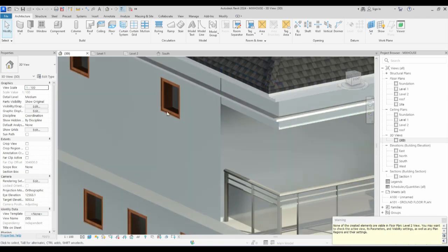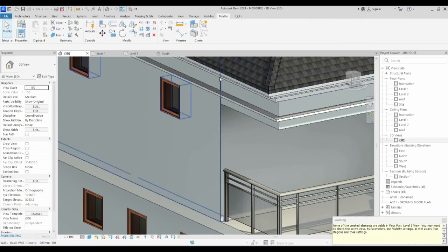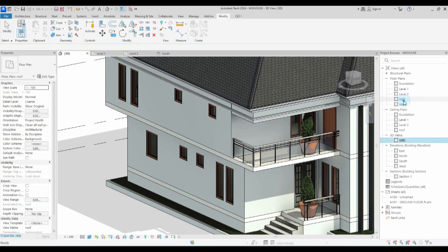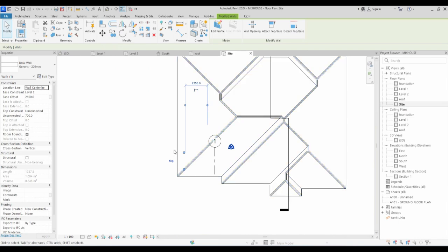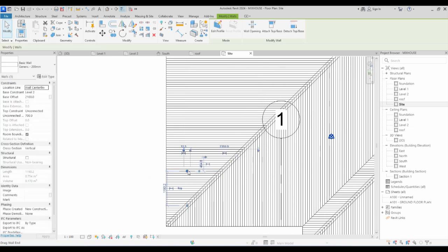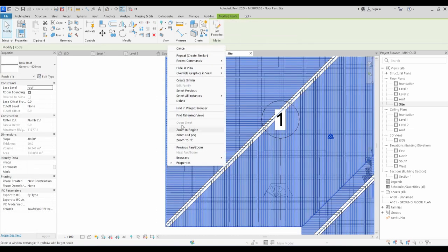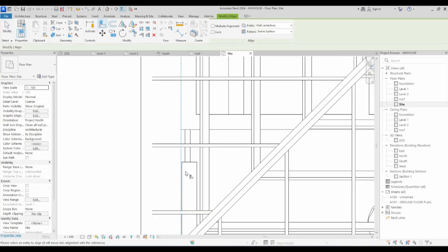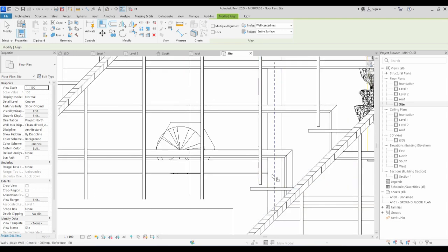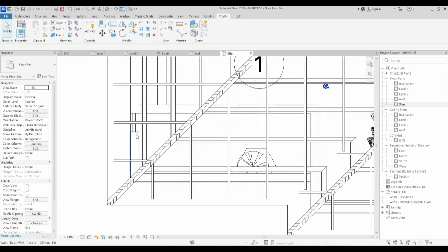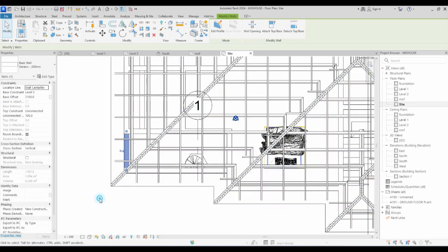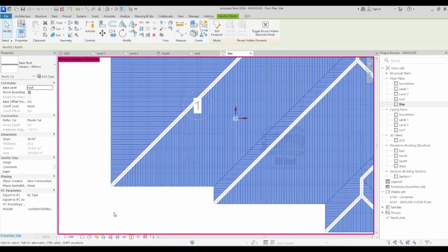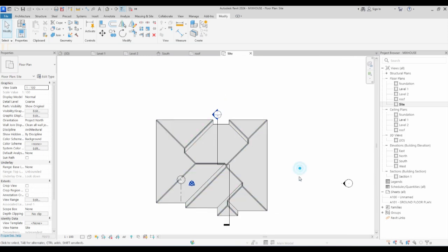So what else do we need to do? You can now align this one so that the whole thing will visually come together and set the standard. So you go to, let's say, roof level, and you can adjust it by clicking it down a little. Here you click, let's say, hide the element temporarily. I want to align it to the wall so that you have the same level. This one doesn't have the same level with anything, so you can stay wherever you wish. Then you unhide the hidden elements by clicking this one, then say unhide the elements. So you come back to normal, then you close this up completely. That is what we've done here.